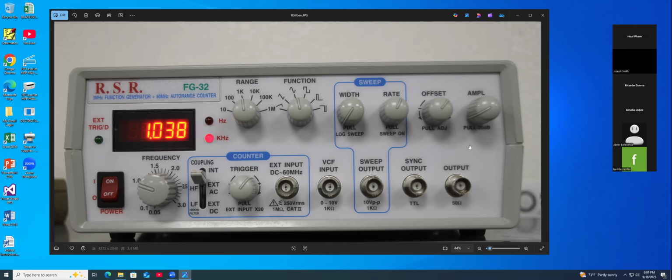And I can tell you one thing. So then you could use the amplitude. But as I said, when you turn the amplitude down to the minimum, they give you only 2 volt or higher. You cannot get 300 millivolt. So then you have to use the offset of the sync. Exactly.